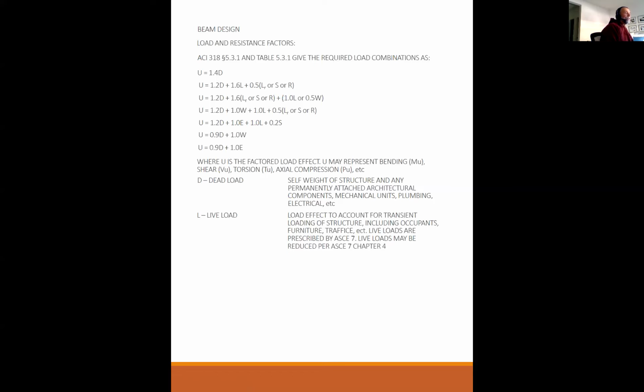And after doing parking garages, not me personally, but we've been doing parking garages for 75 years now, it's been deemed that 40 pounds a square foot is an acceptable design, and nobody's seeing any kind of failures in parking garages. So my point is, that's all done by ASCE 7. They're the body that has the resources and the research to figure out if these loads are adequate for what we're trying to do.